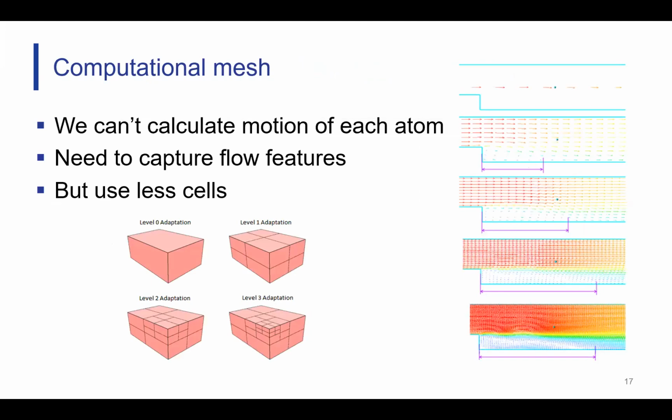Next, our discretization stage. As you recall, after the modeling stage, we mesh it, where we're breaking up our model into many blocks. And meshing is a very complicated procedure, theoretically. Why? What makes it so difficult? You have to answer the question of just how many blocks, how many of these boxes am I splitting my model into? And that's really hard to say. Your task here is to accurately capture the geometry and the flow features. So for example, if you have a region of turbulence or high gradients, this is going to affect the flow. This is the behavior of the flow that I want to capture as well as possible.